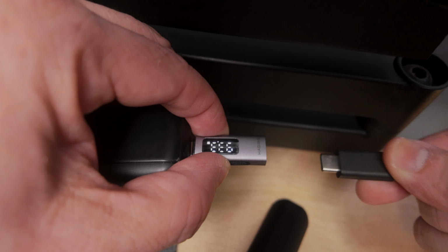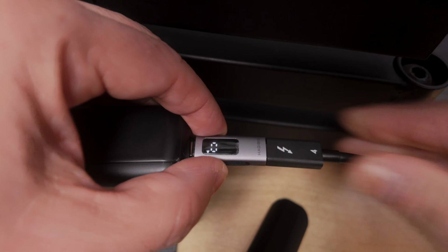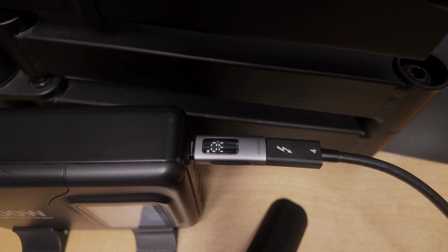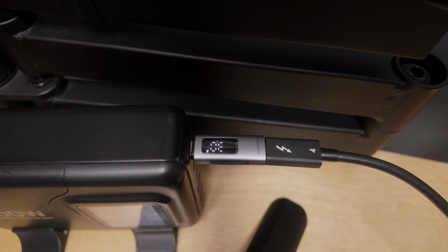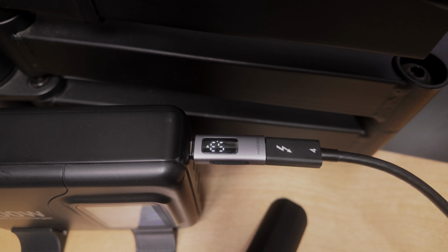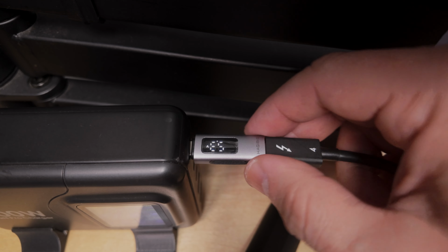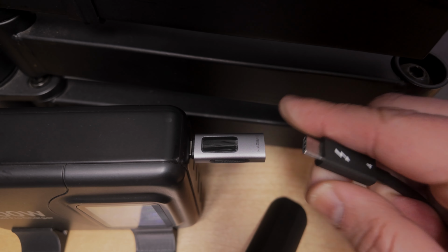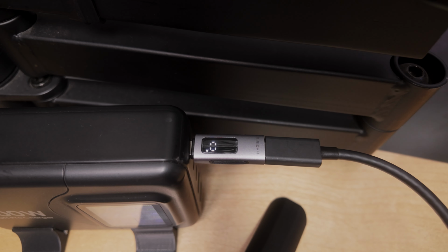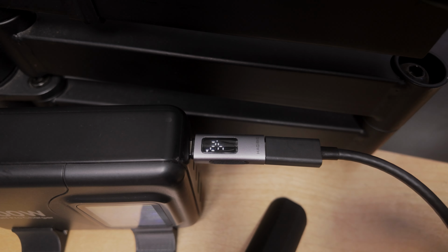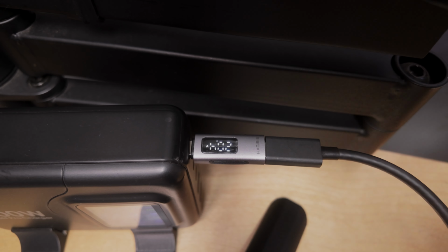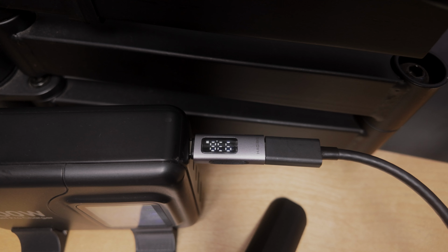Now, if I were to flip this cable like we did earlier, we'll see the same information where it's going to cap off at 5 volts, 3 amps. So there's 5 volts there, 14 or 15 watts. It's showing 15.9 watts. So as you can see, it's giving you the information here to let you know that in this orientation, you're not getting the full speed. So all we got to do now is flip it over. And immediately it negotiates the higher voltage and wattage.